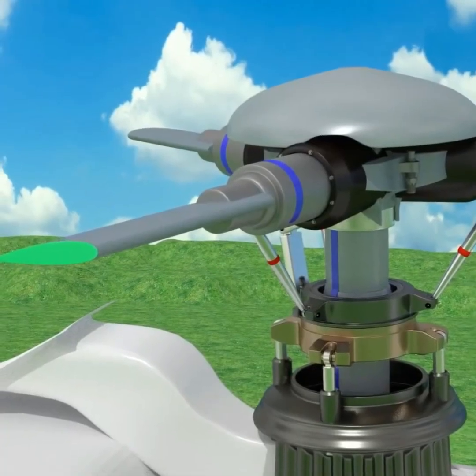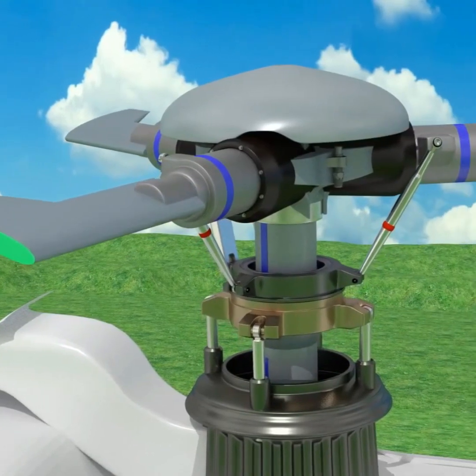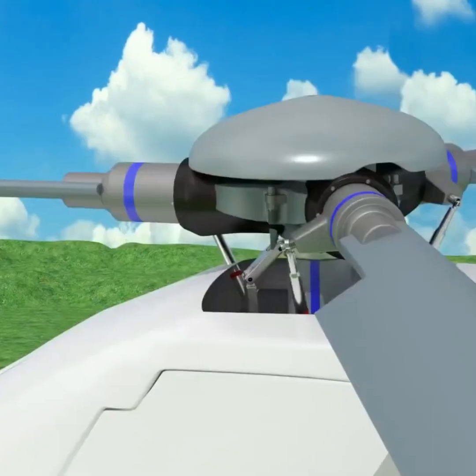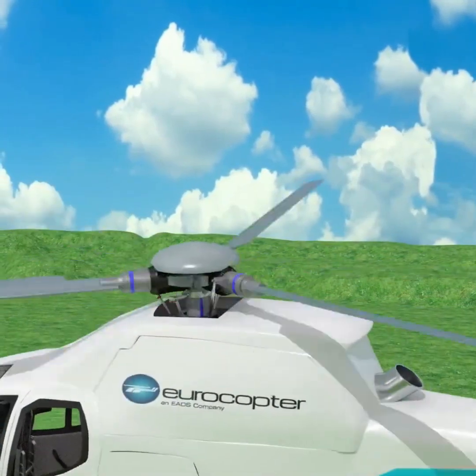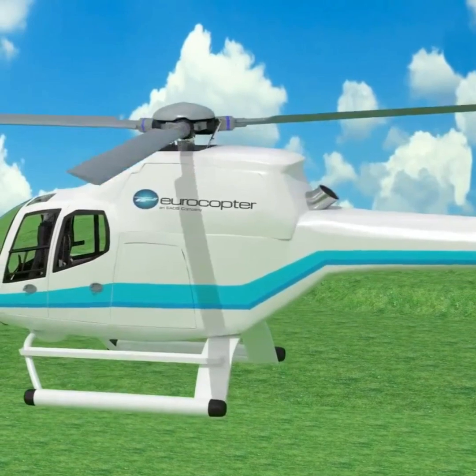If you lift the lower swash plate without tilting, the angular momentum of all three blades will change equally. This means that the lift force of the helicopter will be equal across all three blades, and the helicopter will be able to move up or down without tilting. This type of blade control is known as collective pitch.